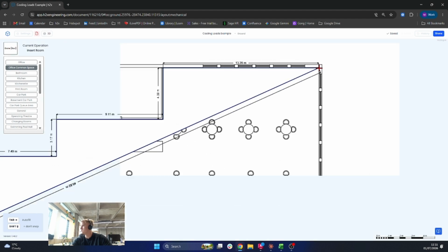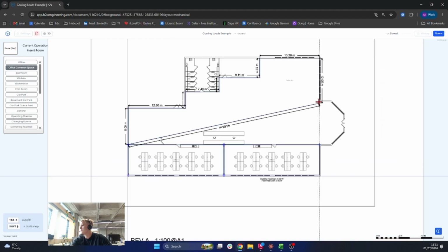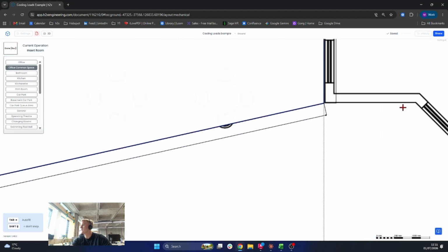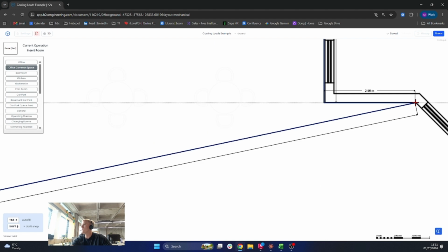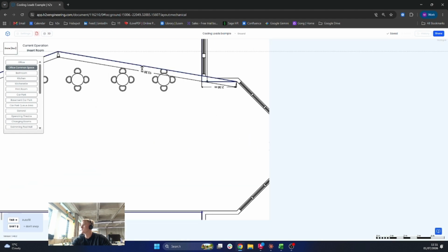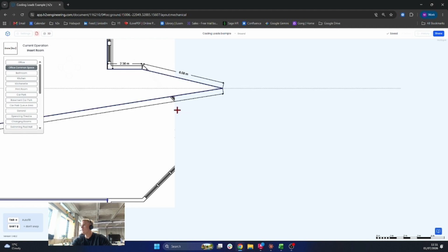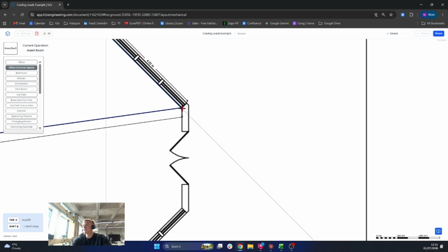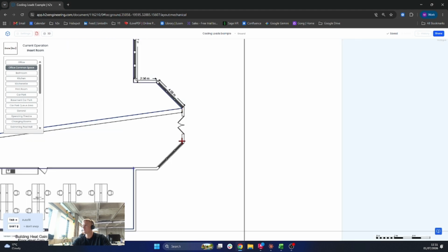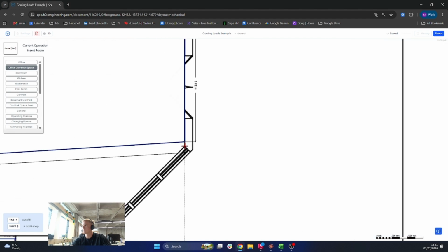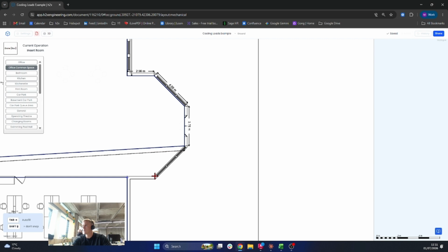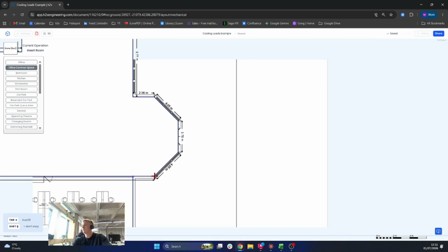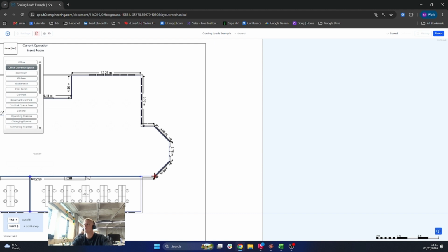Now, obviously the software is cloud-based, so it might not have the reactivity of software that is downloaded like AutoCAD or Revit, but if you essentially make sure that you add all of your points, scroll around where needed, don't panic if the PDF takes a little bit of time to load up, it will come back eventually. Just make sure that you add all of those internal corner points. Just like that there. One here, one there. And you'll see that H2X will also give us guides to let us know that we're on 45-degree angles, 90-degree angles, or whatever it does need to be.